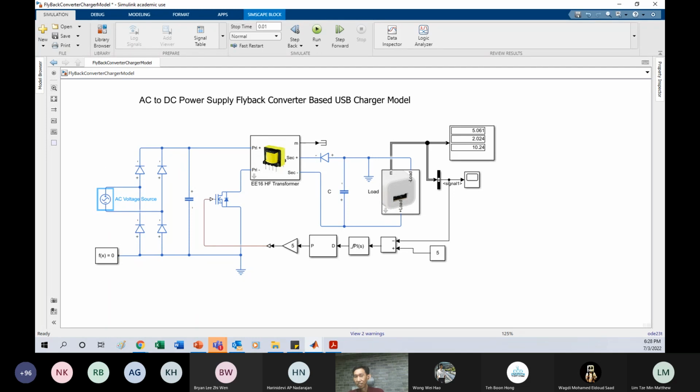Oh, so for buck and boost, they cannot behave like this, is it? Buck and boost, not that they cannot, but not as good as this one. Because buck will only step down, boost only step up, and it doesn't provide insulation. It can in some way, but not as good as this one, because imagine if this is no good, your handphone charger is using this one, can you trust or not? So many years already, can, right? Our computer power supply is using this, and you bring it to another country, you don't need to worry about this.